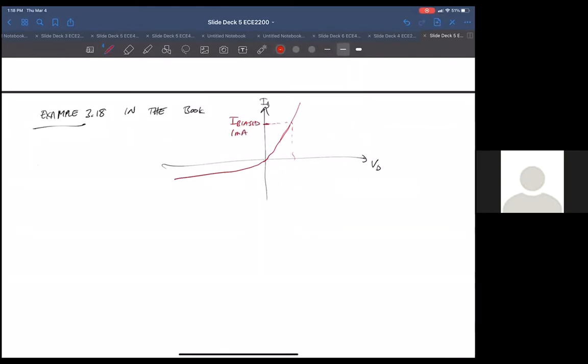So that's where your diode is kind of centered around. And so this gives you a corresponding V bias. Once we have the I bias for this problem anyway, we don't even need to calculate V bias, because remember, R sub D is just a function of I bias. But anyway, we'll get around to that. So we're based on I bias, and the question is, how much would I bias change if V bias changed by, so if delta V was 1 millivolt, what's delta I?